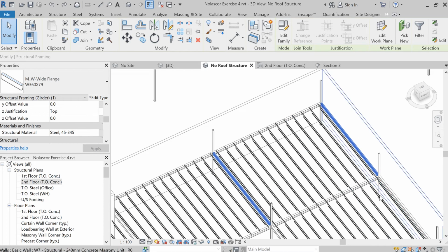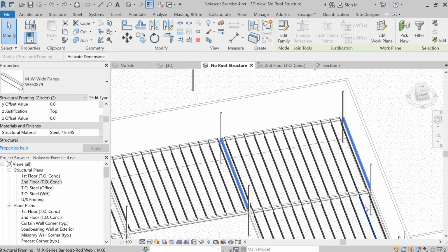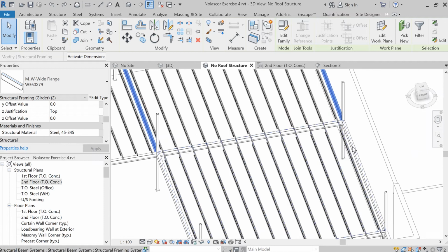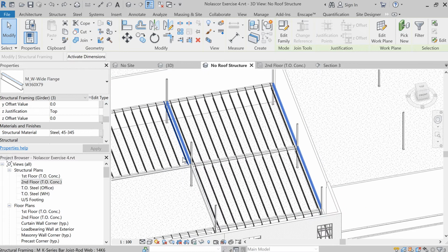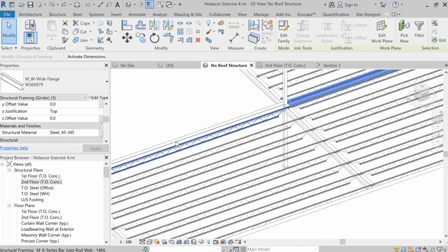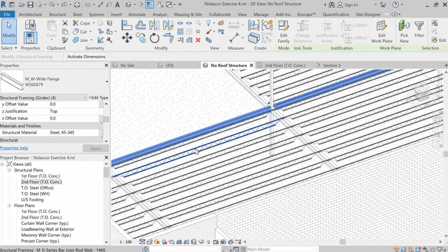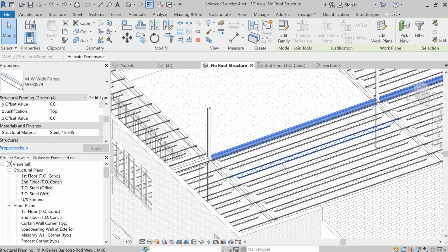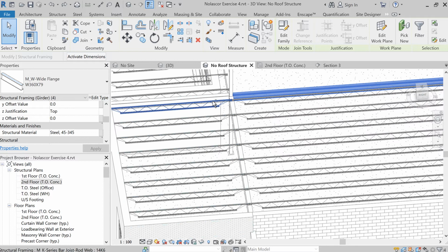Unfortunately, we cannot use the filter method since we're actually lowering the beams with different heights. So I'm just going to select this. They're not that many anyway. So pre-planning is also important. Even if Revit means revise it, well, not revising is still a lot faster.